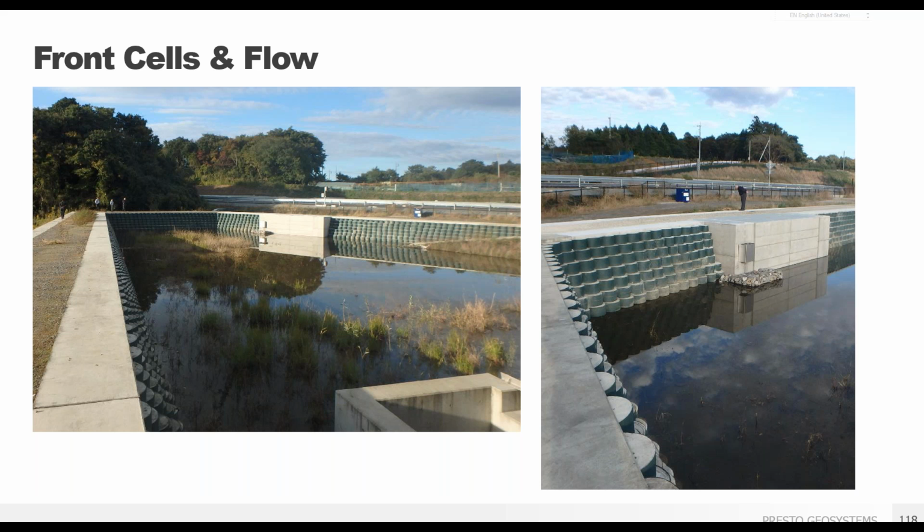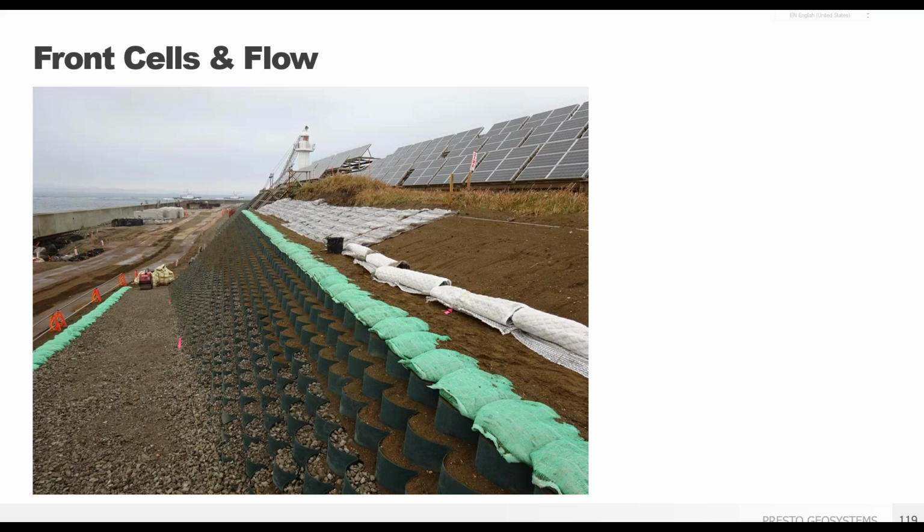We mentioned drainable fill a few slides back. You may also consider grouting the front cells or filling them with concrete when high flow is expected, like this highway retention pond. Or a mix of medium, as you see in this project, with aggregate fascia along the pathway and topsoil for vegetation elsewhere.